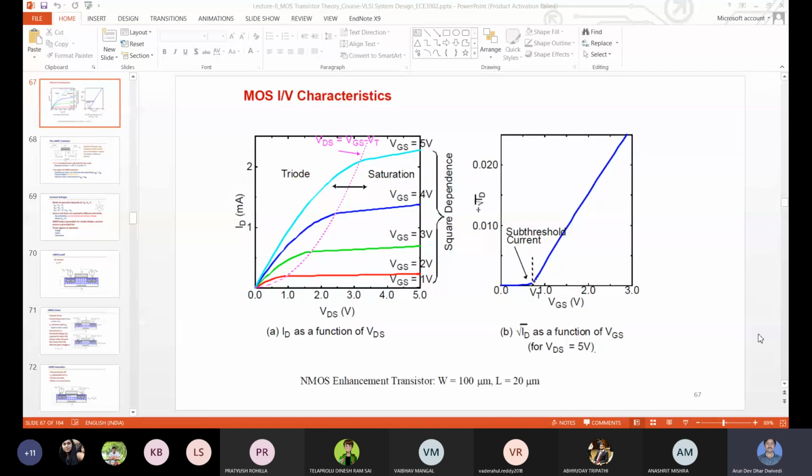In last term we have already learned how to use LT Spice. We got familiar with LT Spice. Also we have done the NMOS characterization. We have done ID versus VGS characteristics. Also we have done ID versus VDS characteristics of NMOS, and we have plotted a series of plots. ID versus VGS we have plotted for different constant values of VDS, and similarly we plotted ID versus VDS with constant values of VGS.